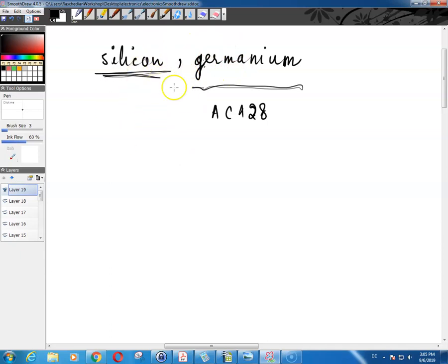They refine them to a very high level, and then in order to control the behavior of those semiconductors, the semiconductor in the factory goes through a process called doping, meaning that controlled amounts of impurity are added to certain regions of the semiconductor. Then, depending on the doping material and how much of it has been used, the semiconductor behaves in certain ways, which is of course predictable because we have control over the process of doping.